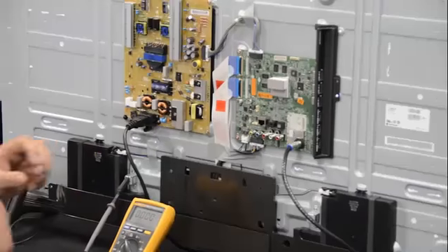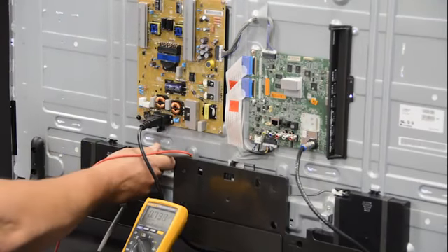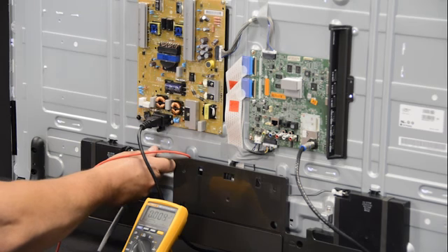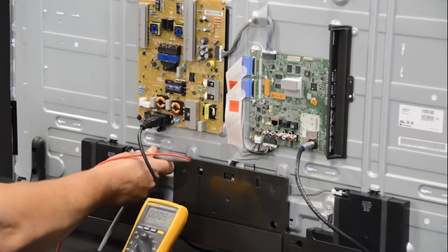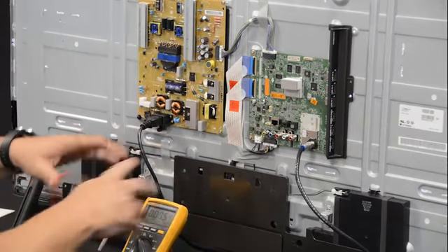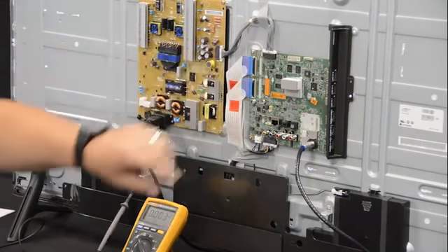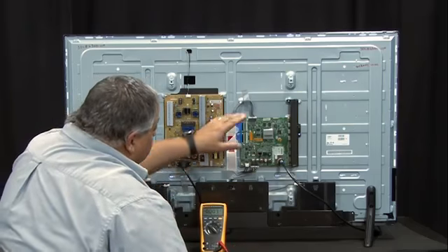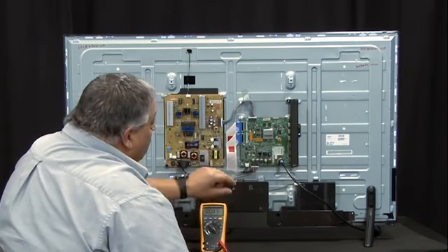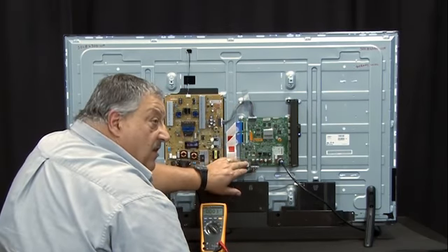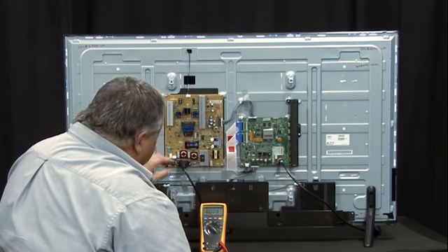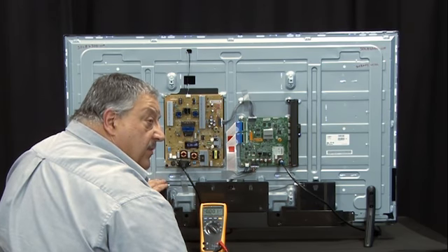Then the next thing you want to do is confirm you have continuity between the output and the speaker. Now you can do that one of two ways. You can unplug it and go into the end, or you can read on both sides. Now if you've got your 1/2 audio B+ on both speakers, you know that I'm producing 24. You know that I'm getting 24 down to the audio amp. You know that I'm driving the speakers with audio B+.